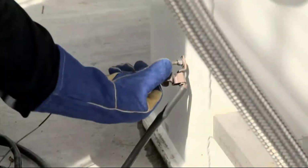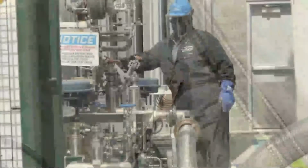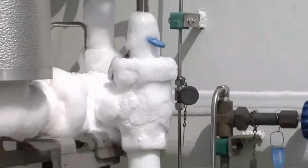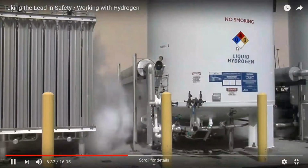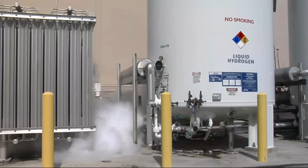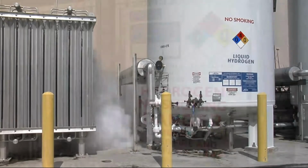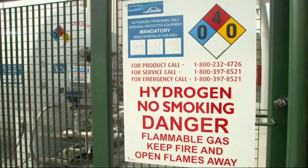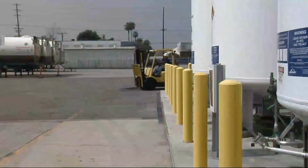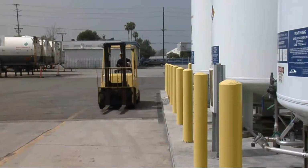Also, the truck must be grounded to the local bulk handling system before unloading to help prevent sparks. Employees who work around hydrogen should always be aware of any unusual conditions that they see at the tank, such as excessive icing, discharge of liquid or excessive vapor from the tank, tank piping, or a safety relief valve. These are not normal conditions, and they indicate a problem. If any of these conditions are observed, call the Linde emergency phone number posted at the tank. The piping should be located in protected areas where workers cannot damage it when they're using forklifts, trucks, or other equipment.